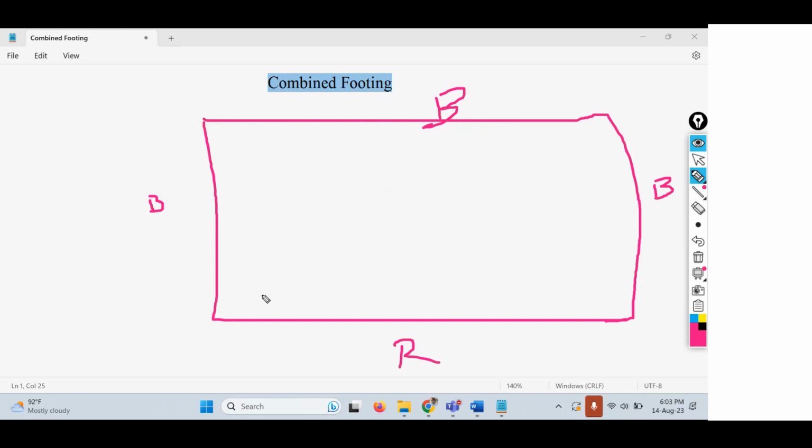Now, what's the simple thumb rule? The thumb rule is that one footing should be there on each corner of the plot or site area. This we know. And there should be other footings based upon the size of the plot area. Apart from these four corner columns, let me keep a couple of columns or footings at the center of the sections as well.